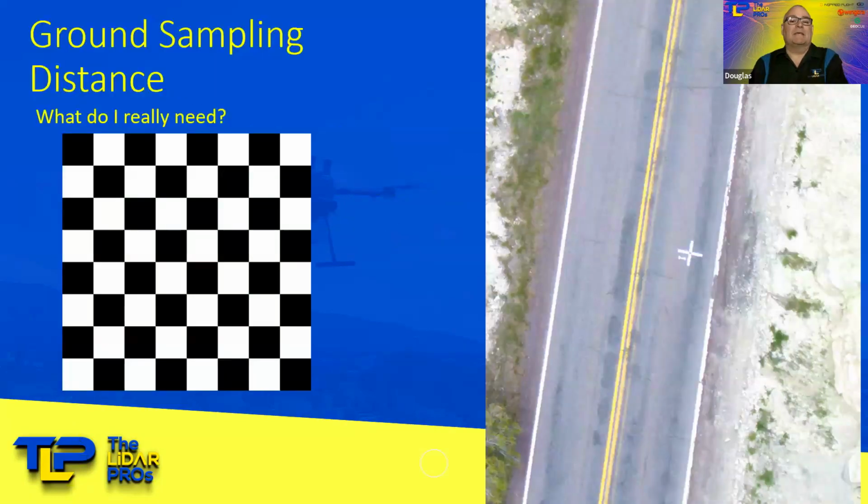Another thing that we want to be thinking about as we're setting up our mapping, or going into planning for our mapping, is what ground sampling distance, or what we call GSD, do we really need to have? Of course, a lower GSD is always better, especially when we're dealing with lower resolution cameras, such as the very common 1-inch cameras that we find on things like the DJI Phantom 4, the Autel Evo 2 Pro, and some of these other 1-inch camera sensors that are out there.